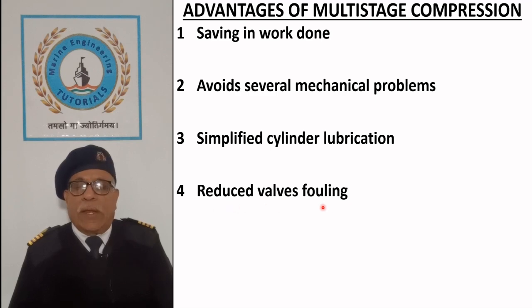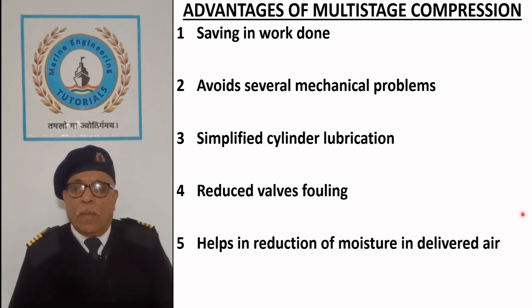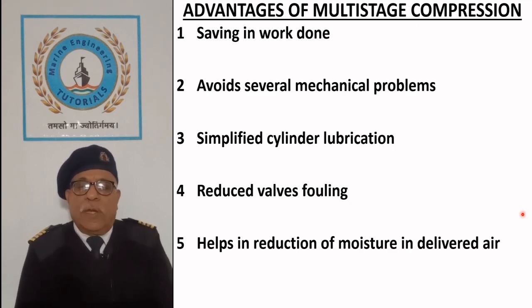Reduced wall fouling. Low temperature of air reduces fouling and carbonization of lubricating oil and maintains valves in cleaner condition. Helps in reduction of moisture in delivered air, which is undesirable in compressed air systems as it causes corrosion.